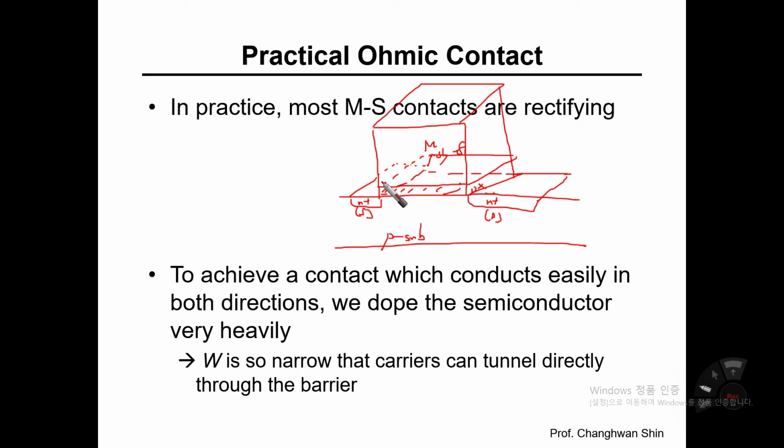The titanium nitride has been deposited right onto the gate oxide layer, and even the gate oxide layer has been replaced with hafnium dioxide, a high-K material. Some more advanced things will be studied in the lecture to be offered next semester, but in this semester, we're going to stick to some fundamental and basic things.